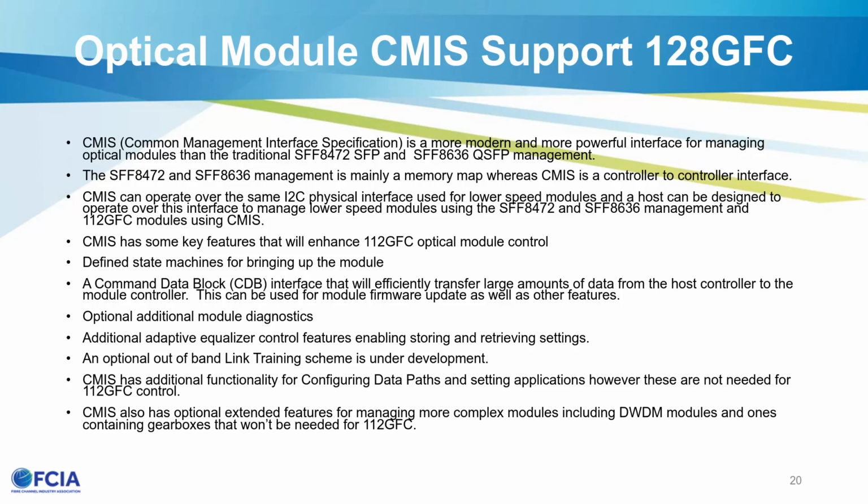And the timings on Fibre Channel, and this has always been key, and I know there's been a lot of discussion about link up times and stuff like that. The timings to bring a link up have gotten longer and longer because Fibre Channel goes through link speed negotiation automatically, which identifies the maximum rate at the other end, and then does training to make sure that we have the link quality we need before mission mode.